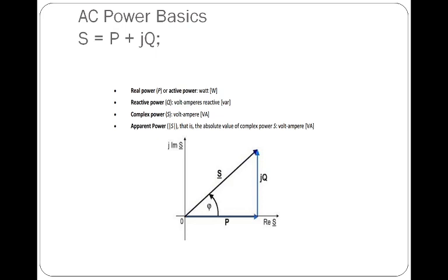That's current and voltage reverse their polarity at the same time. So at every instant the product of the voltage and current gives a positive value, indicating that the direction of energy flow does not reverse. In this case, only real power is transmitted or transferred. So for purely resistive load, we get true power.